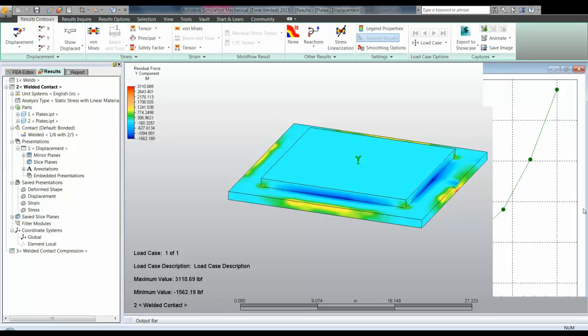There are other techniques that would allow you to not have the weld in there at all, and maybe that's something we could look into for a future presentation. But whenever you do these approximations, you're obtaining less detailed results as well. And so the idea is when you're approximating the details of something, you're looking at the overall results, more like the stiffness and deflections of the model, or maybe the stresses in other locations, not necessarily the stresses in those particular locations.